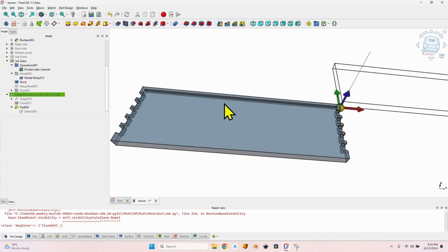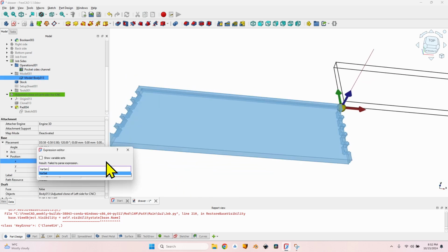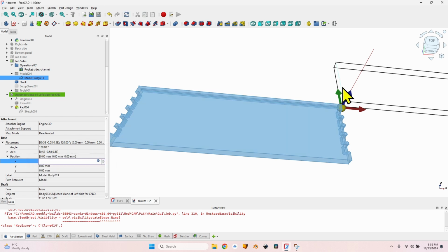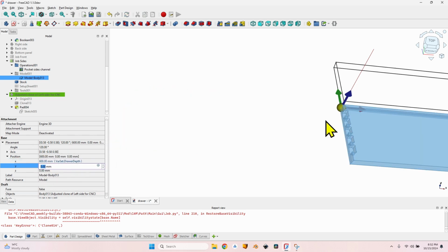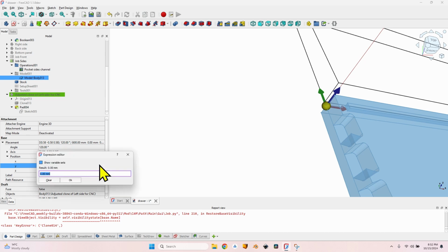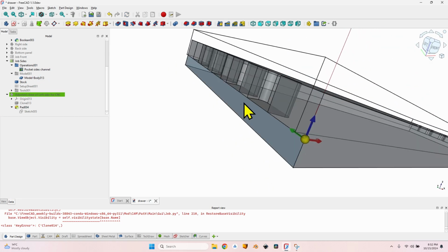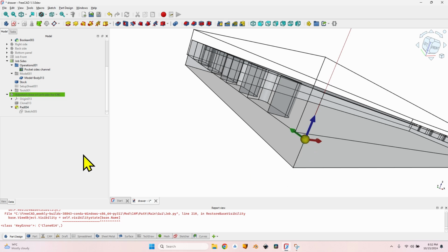Now we still have to move it. Go to the placement position. On the X we are going to use the drawer depth, and as I've explained to you earlier, it will position correctly because that offset was already there. Let's also modify the Y. It is going to be VarSet drawer height. This is the height of the sideboards, and now the origin is correctly placed. I don't care about the length of this pod, and that is because it goes from the origin downwards.